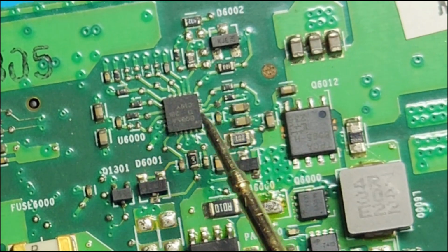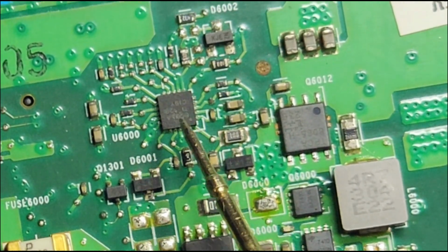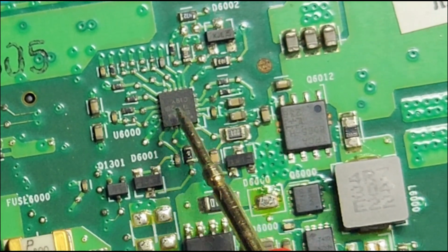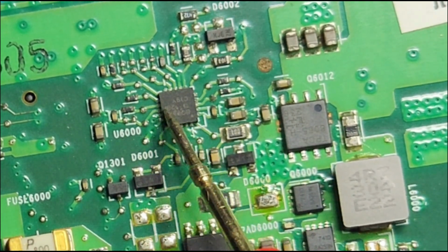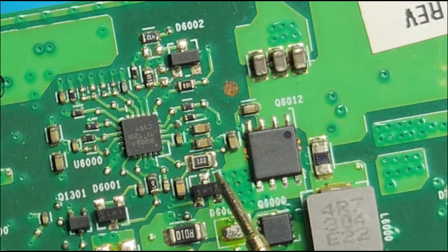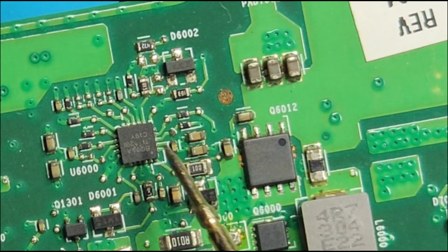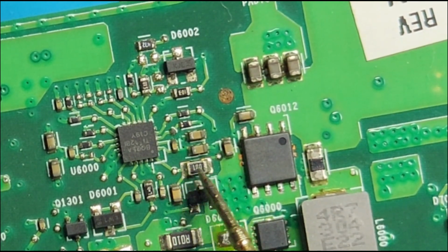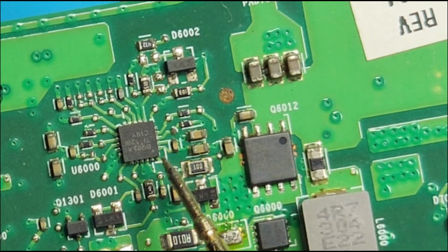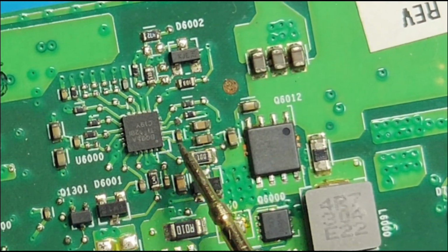So we should check whether the input voltage for the charger IC is okay, then the LDO output, which is the REGN or VDDP. If we have the REGN, it is 6 volt, and if we have VDDP, it is 5 volt. So here we have the input resistor for the charger IC. We should check whether the input resistor for the charger IC is okay and the charger IC is outputting the LDO voltage correctly. Okay, so we need to check that as well.